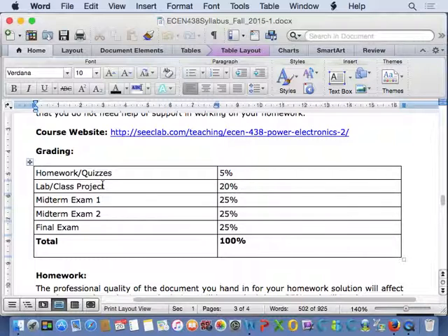But some UPSs are direct online. Some UPSs detect when a system fails and then they come online, right? If a UPS is direct online, it's seeing power pass through it all the time, then the system will probably have to be designed for higher thermal losses because power is being transferred through it all the time, versus a system that is on standby. It's not generating power all the time, it's waiting on standby, it's not turned on, it's a different system, right? The size of that may be smaller, the losses in that will be smaller, right? The battery size in that will be smaller.